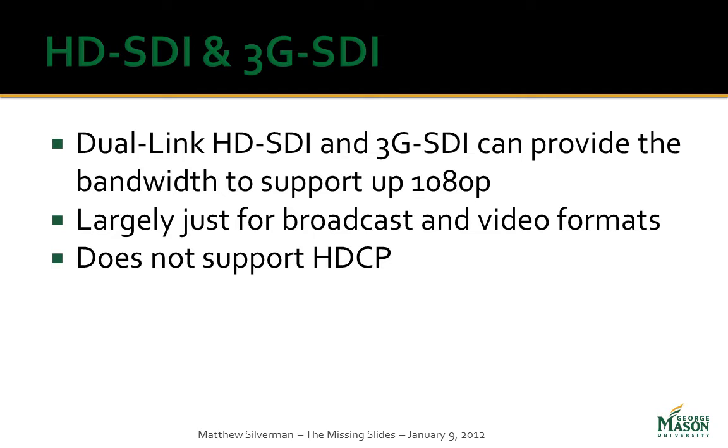In the one application I've looked at integrating them, the problem I ran into was no HDCP support. I've looked at a couple of boxes which do conversions, but again, HDCP is the problem. They're really designed to move video around the studio environment. They're not designed to be a presentation format or a data format. That's really where you get into HDMI or DisplayPort. So I wouldn't really consider these viable formats for putting together a classroom system at this point in time.